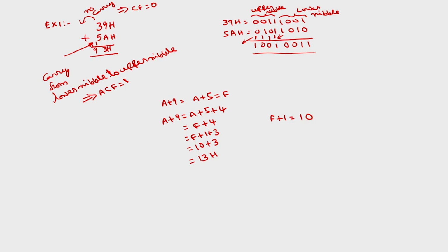There are two instructions, like decimal adjust accumulator, DAA. While discussing the instructions, we will see that this auxiliary carry flag will be used in this instruction. Similarly, we have decimal adjust after subtraction. These two instructions use the auxiliary carry flag. Coming to the fourth conditional flag, which is the zero flag.